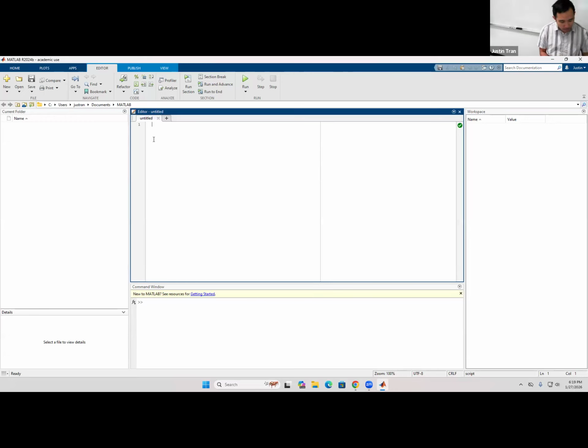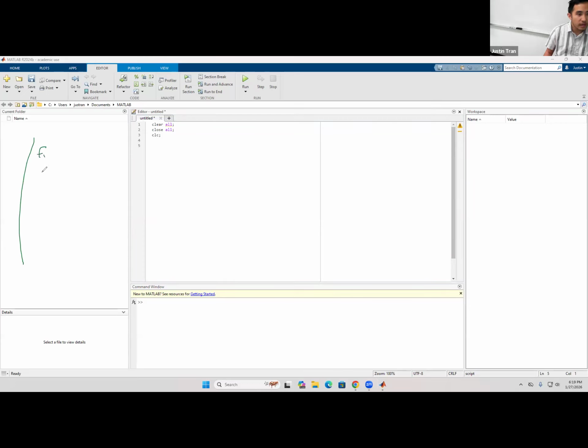So we have our forcing vector. Actually, let me do this just because I'm OCD. I have to start every script with clear all, close all, clc. Essentially, we need to define our vectors here that are going to be part of our linear system. If you remember, we have a vector with F1, F2, F3, F4, and then we have our matrix of values. These all come from the element stiffness matrices. And we have D1, D2, D3, D4.